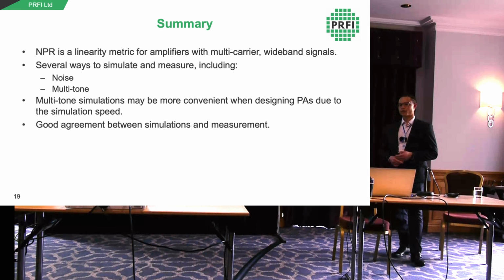NPR is a linearity metric for amplifiers with multi-carrier wideband signals, increasingly seen in SATCOM and defense sectors. There are several ways to measure and simulate it, but the 2 most relevant ones that we see are using a noise signal, as is traditional, and then using a multi-tone signal, which has advantages in simulations.